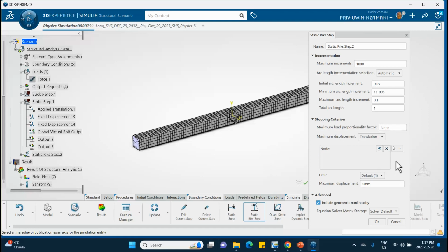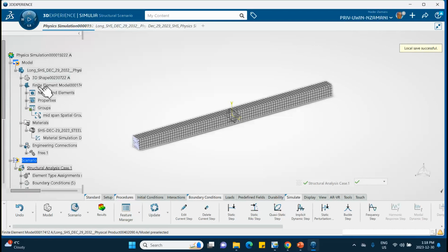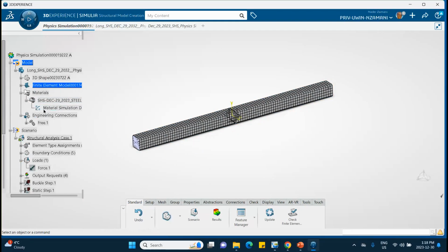So what I'm going to do temporarily, I'm going to say okay and come back to this window later on. What I'm going to do is I'm going to create a group I called my selected node, and then use it later on. So I'm going to say okay. Anything that I've done here so far is taken. So you have to create a group. In order to do that, we can go to the model, final model, the same place that you created the other group.